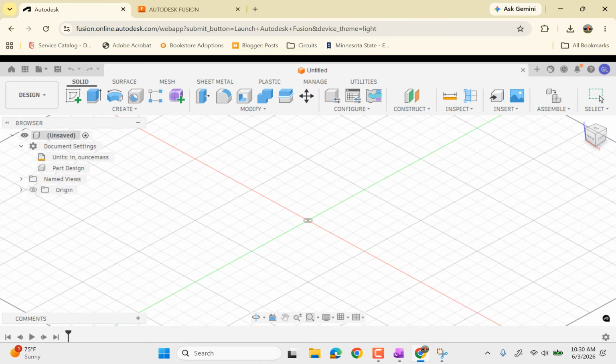And in order to do a revolve, instead of sketching the entire cross section, I'm just going to sketch 1/2 of it. And then we'll do that 1/2 of it a full 360 degrees. So what I'm going to draw is something like this. Okay. And when we do the 360-degree revolve, it's going to put this other half here.